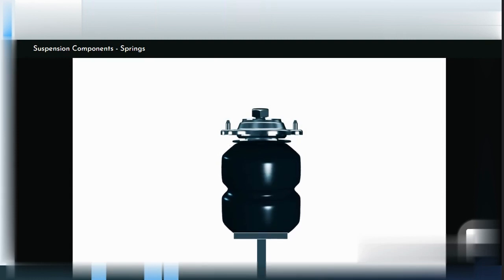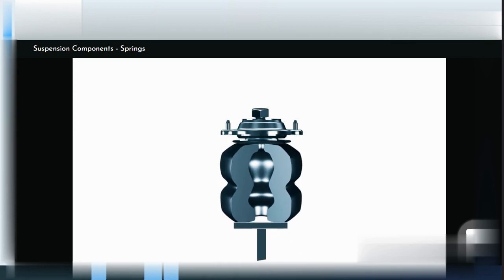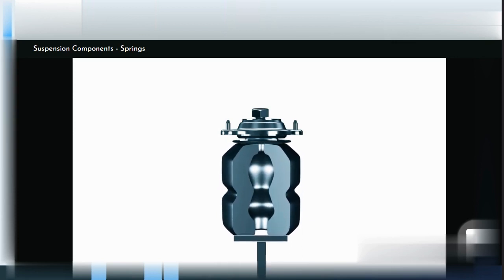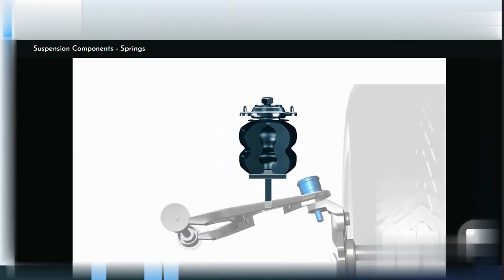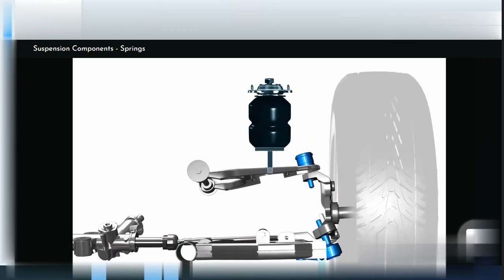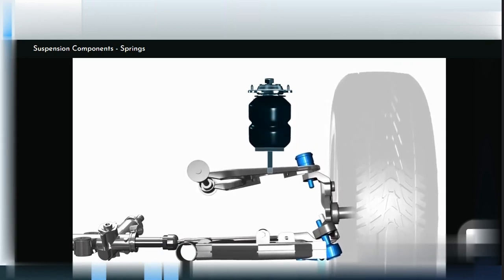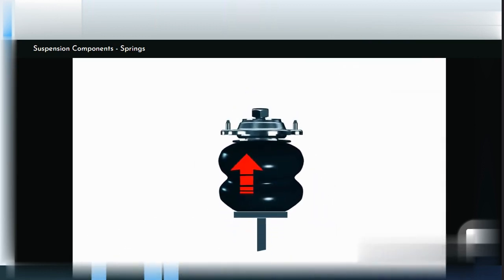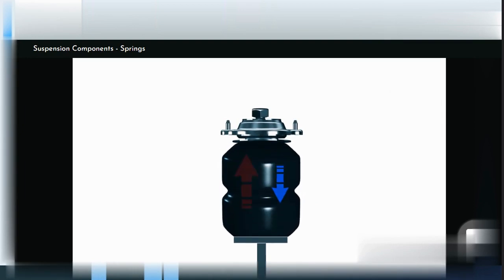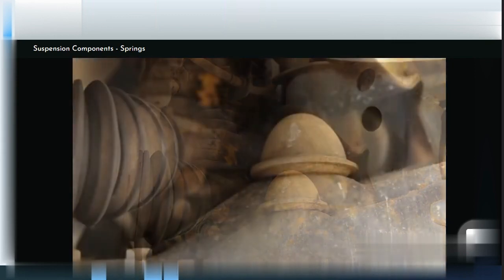Rubber can absorb large amounts of energy with considerable weight savings over steel. Rubber springs work on compression and can be used as the main suspension spring or alongside the metal springs to improve the suspension's characteristics. The spring is installed between the K-frame and the top control arm. This arrangement of springs provides a rising rate effect, which is soft for small wheel movements but becomes harder as the spring deflects. The energy released from the rubber spring after deflection is considerably less than originally applied to it. Rubber bump stops used in many suspension systems aid the main spring against maximum deflection.